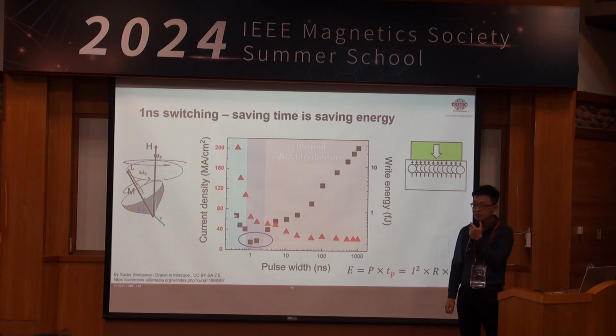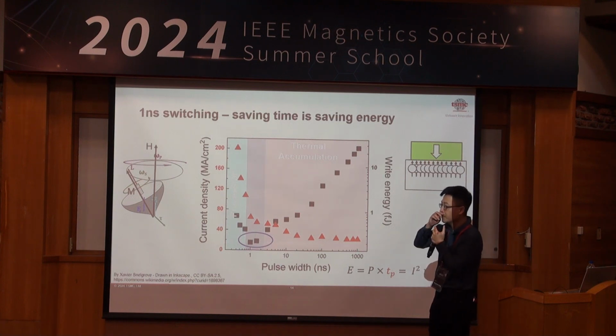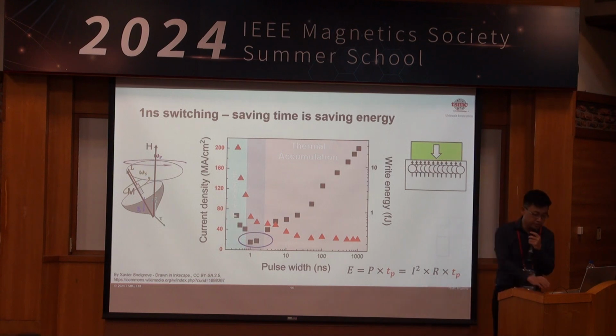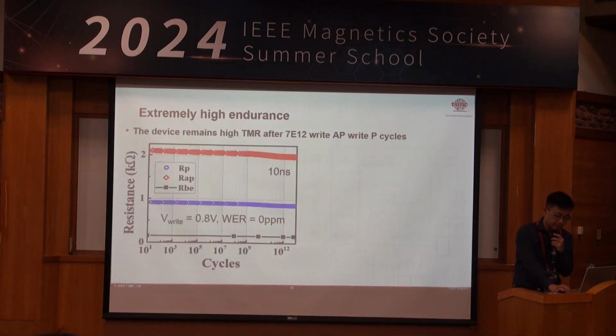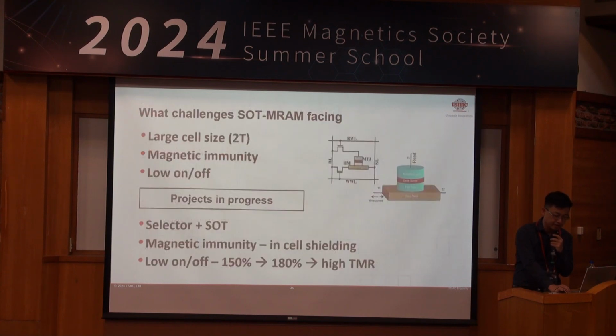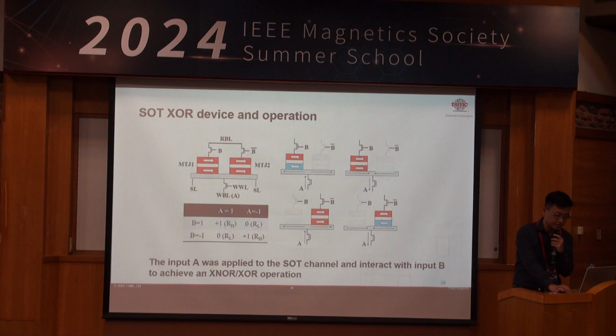For the MVM operation, a 1T1R array is sufficient to do this, so I'm wondering about the purpose of using the MTJ pair. You mean for the MVM operation? Yes, a 1T1R array is sufficient. If you want to do this, you can use one transistor to write it, and then control the word line.